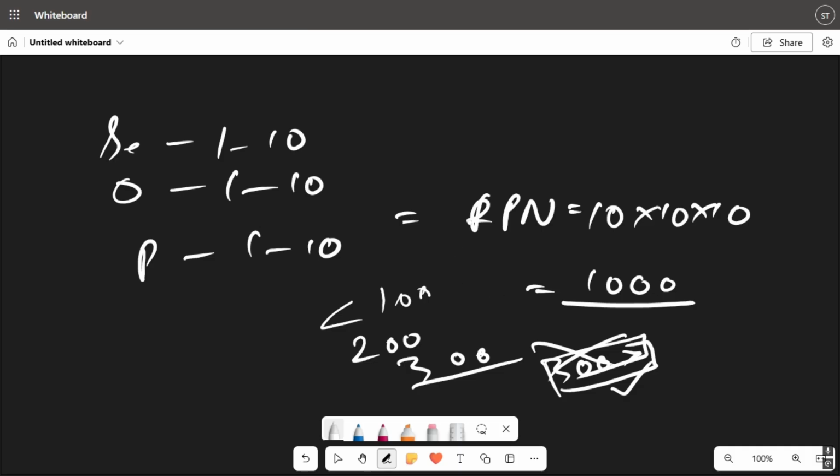After which, for example, if we have the column for the before analysis, you can think that it was about 400. So we have to revise it and take the recommended actions to reduce your RPN number. Then, after assigning the reduced severity, occurrence, and detection values, we can assign the next RPN number by calculating it.